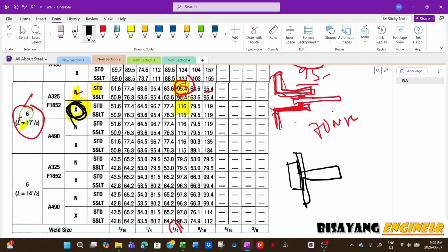So you have a washer, and then you have the shear plate thickness, and then you have the width. You just have to make sure that this shear plane is not located in the thread portion. So usually the thread is right here, so you can put your nut. So as long as this is the case, then you can use this value.